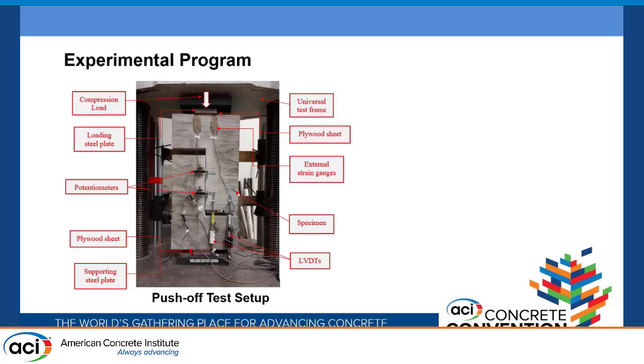Basically, the push-off test is a compression test where we want to create a relative displacement between the 2 blocks that conform the specimen, and this relative displacement is possible because of those gaps intentionally left during construction. So when we produce this vertical movement, the reinforcement that is crossing the shear plane is engaged in the mechanisms and contributes to the interface shear transfer capacity.